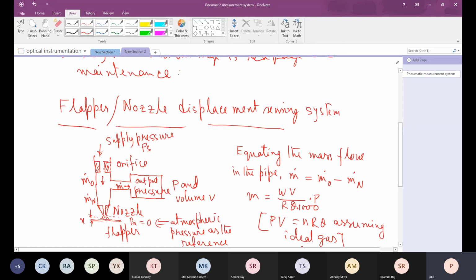So we are restricting this area through an orifice, okay, we can do it also like venturi, etc. But correspondingly, whatever restriction element we use, the discharge will be controlled corresponding to a formula given by that particular